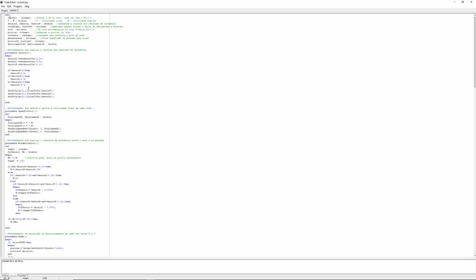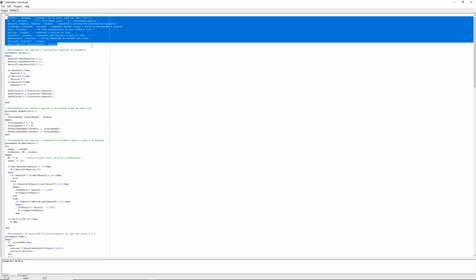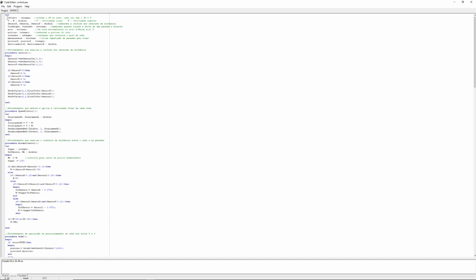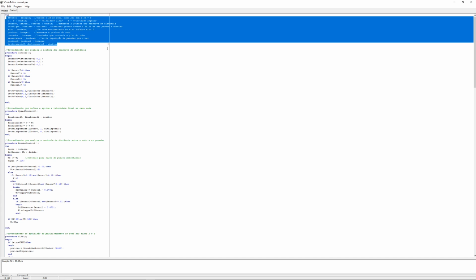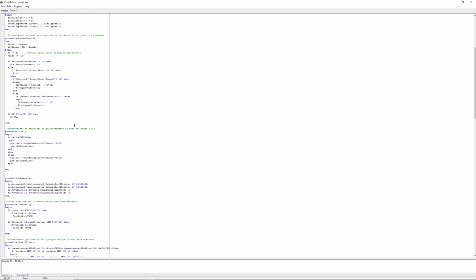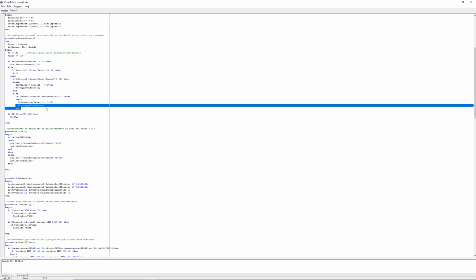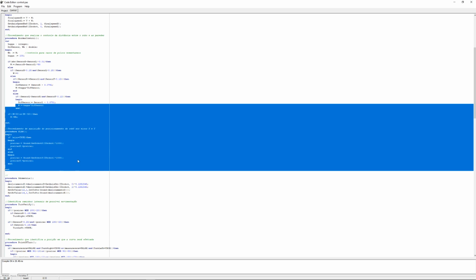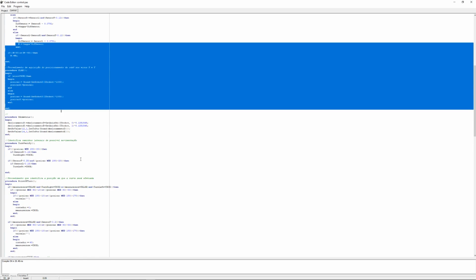Pay attention to these notes here at the top, the comments. That's very important to know where you're going to store the position, in case there is a fault, so that you can keep track of it. And here's your code where you can define the decision making of your PID loop, controlling your robot based on your XML start definitions, the PID that you gave in XML.